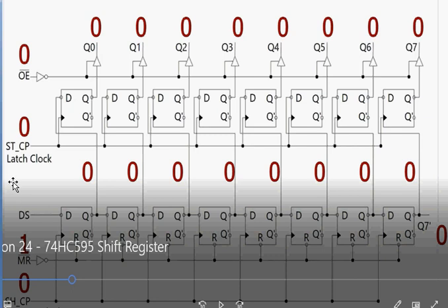So how do you receive data? As we know, P21 will be connected to DS, so one bit at a time can be fed here. Assume that you have the data 101 in the buffer, and we want that data to be pulled onto the shift register. First we make the clock bit initially 0, which implies you don't have information. If one bit needs to be transferred to this end, then apply the clock.